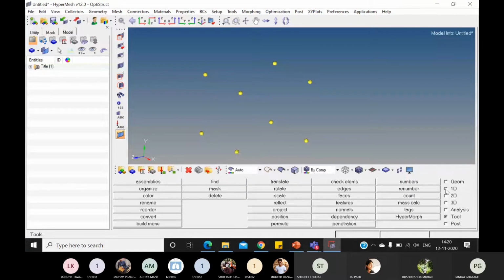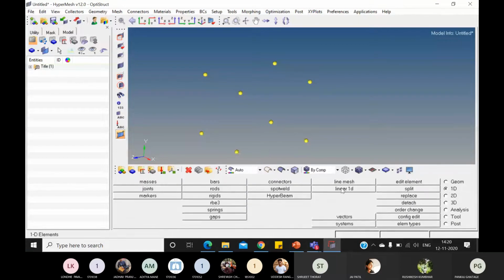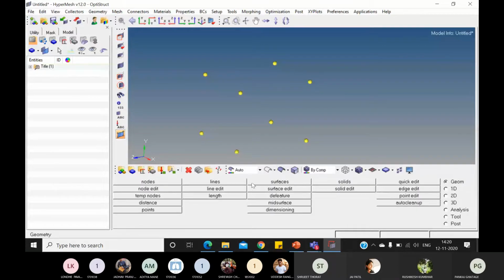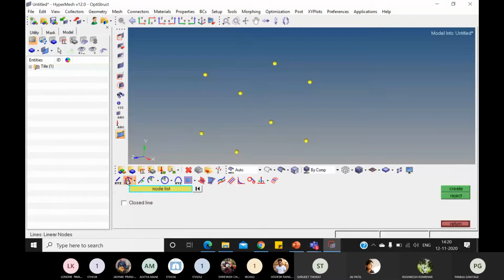So how can we connect it? By line. Go to the geometry, then lines, and here click on this part. Then connect this to this, and press the middle scroll button, this to this. You can create it like this, or you can use the shortcut, pressing the scroll button. Okay, press the scroll button. So this is the front part, then this to this.